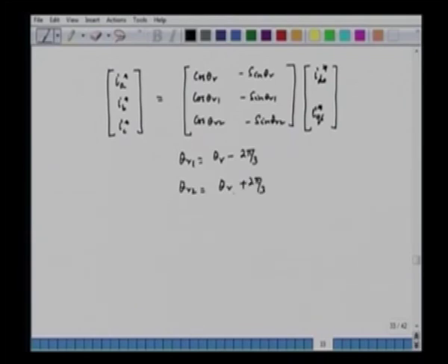So, this transformation transforms IDS and IQS into IA, IB, IC, which are used as the reference for the CRPWM VSI. Now, this is the aspect of implementation. The question that we asked a little earlier is how we are guaranteeing that in a vector control synchronous motor drive the response is quite fast. To understand that, we have to derive the equation for the torque of the synchronous motor. This we have already done in the past.